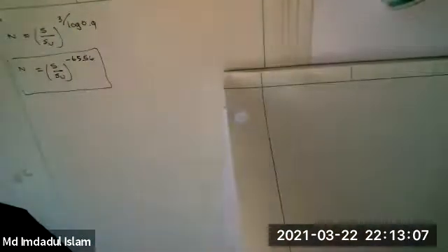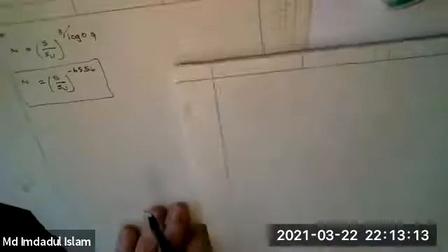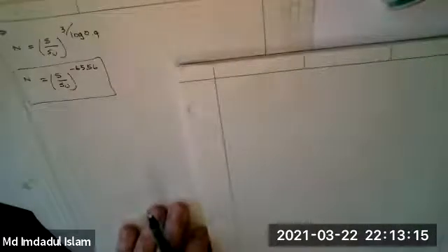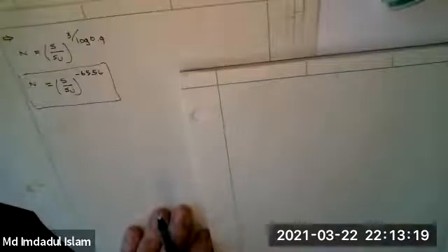So even though it's a test specimen, the lives you get here apply in practice because often shafts are under bending more often than not. And so if they're steel shafts, you can start using what we've got to estimate life. Here's an example.